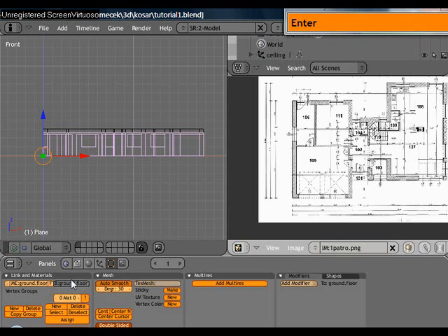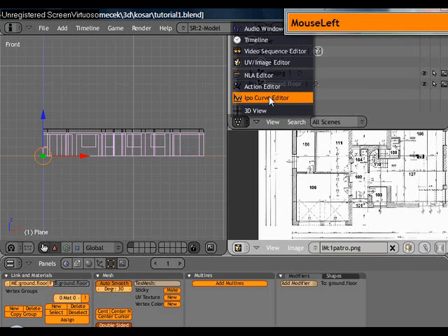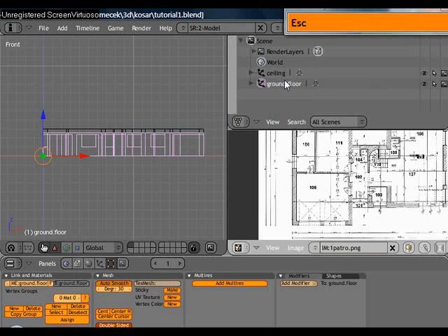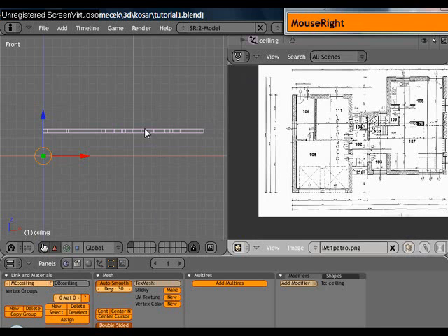The reason I'm doing this is when I have lots of objects and meshes over here, it makes it quite useful to navigate in the outline view in here, and I can even search, and when I select something I can keep selecting like that. So I'd like to keep them nice and name them from the beginning. It's easier than going and renaming them later on. I'd like to also press M to move this object to my second layer, and this one M the third layer.